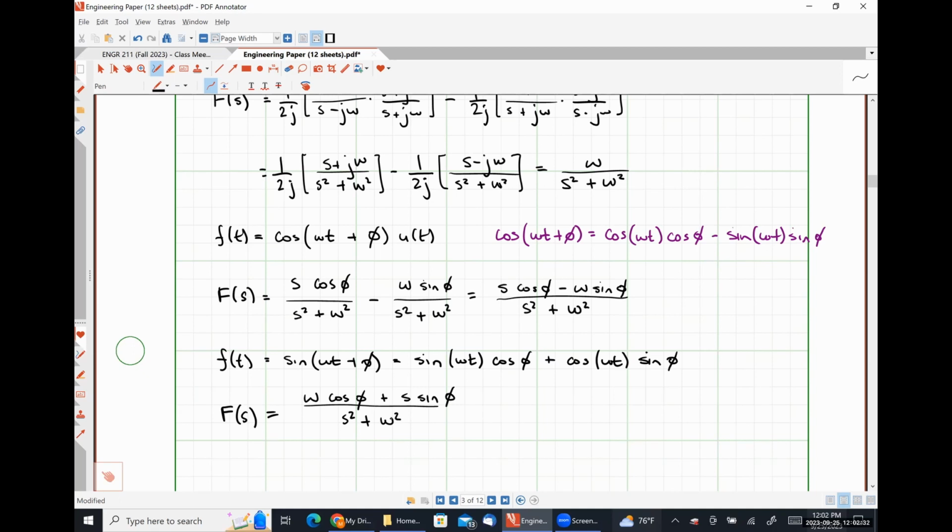And then what's going to happen is the positive reactance of the inductance will be exactly canceled out by the negative reactance of the capacitance, so that the circuit really looks like it's just your voltage source in series with two identical resistors, and then finding average power from that should be a joke for a third-year electrical engineering student. In case it isn't, it's just 1/4 times the magnitude of the voltage squared, assuming you don't have an RMS value. No, excuse me, if you have an RMS value, it'd be 1/4. If you don't have an RMS value, it's 1/8, because you need to add that extra factor of 1/2, divided by the resistance.